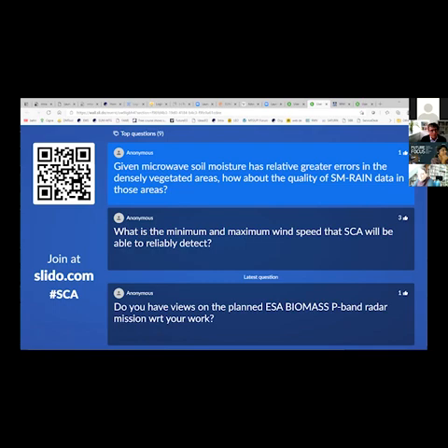But I would rather advise not to use SM terrain in very densely forested areas, in particular coniferous areas may be problematic. We also observe problems in desert areas. Actually, the subsurface scattering, which I didn't touch today, is an even larger area of concern. The areas where the product works best are where soil moisture works best, which is in grassland and agricultural areas. This is where the product quality overall is the best.